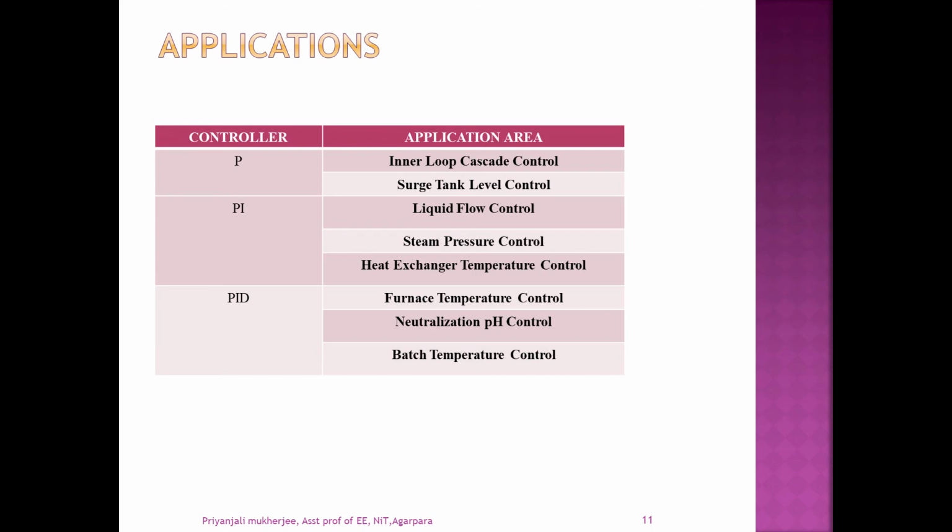Another application is steam pressure control, and pressure is another process type that is often essential to production and exhibits highly dynamic characteristics. With steam pressure control, the prevailing objective is to react quickly to changes in demand from the downstream users while limiting the negative effects on sensitive process instrumentation.